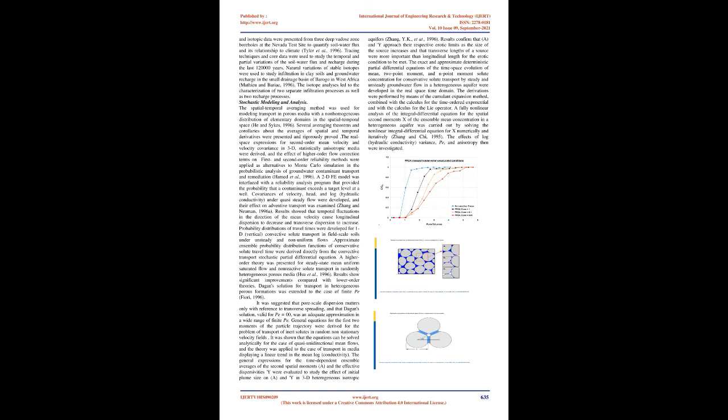Approximate ensemble probability distribution functions of conservative solute travel time were derived directly from the convective transport stochastic partial differential equation. A higher-order theory was presented for steady-state mean uniform saturated flow and non-reactive solute transport in randomly heterogeneous porous media, Hsu et al., 1996. Results show significant improvements compared with lower-order theories.